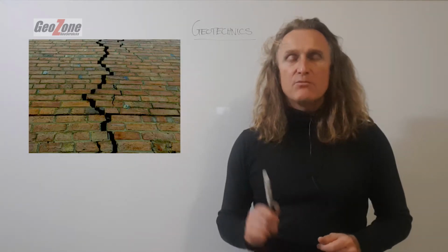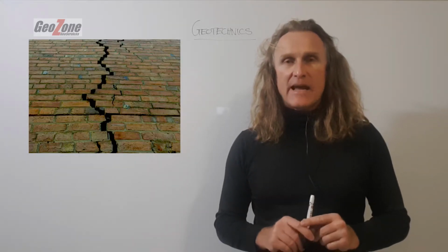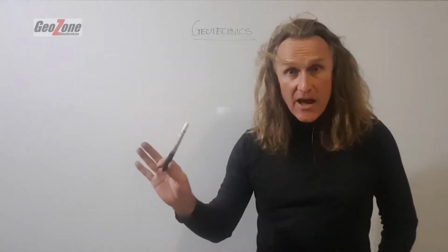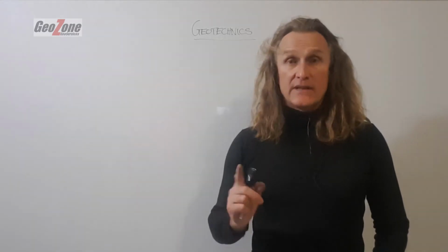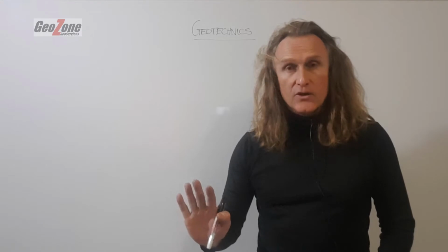In the US, they say the damage caused by expansive soils outweighs, put together, the costs and the damage caused by all those others. Expansive soils take up moisture in the wet season, lose it in the dry season. Ongoing cyclical expansion and contraction of that clay will damage a structure. Expansive soils occur throughout the world.